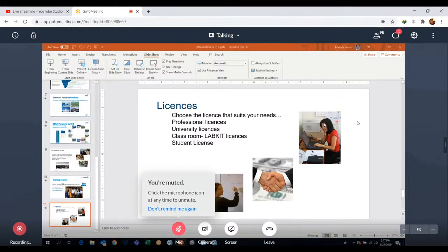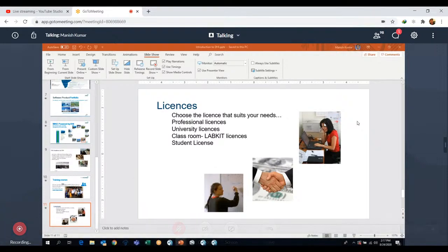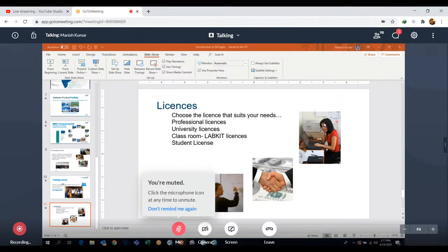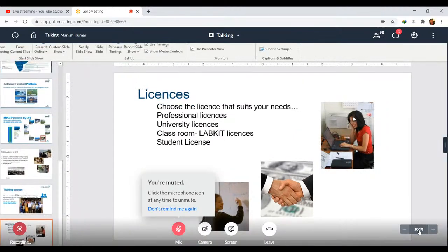You can start your model, this 1D river model, with your DEM available. Normally a 30-meter DEM is available free of cost. So you can extract your river network and extract cross sections in Mike Hydro River. You can use the same file for the 2D model to create your 2D bathymetry file, the DFS2 file.